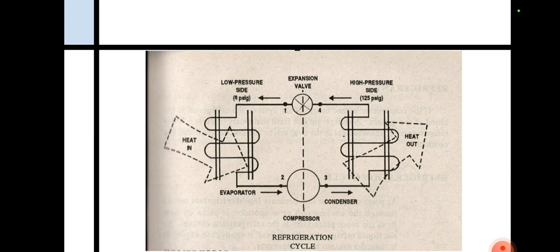The low-pressure gas refrigerant is drawn into the compressor where it is subjected to high pressure due to the compression process done by the piston or cylinder unit of the compressor. Because of the compression, the low-pressure gas refrigerant increases its pressure and also its temperature.